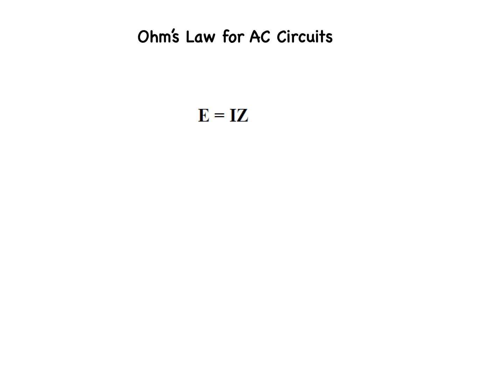Now, if we were going to use Ohm's law using our phasors, reactances and impedances, it would be the same as we would use for the DC circuit, but this time instead of resistance, we have impedance. The voltage is still going to be equal to the current times the impedance. But you have to remember we are using phasors, not absolute values.